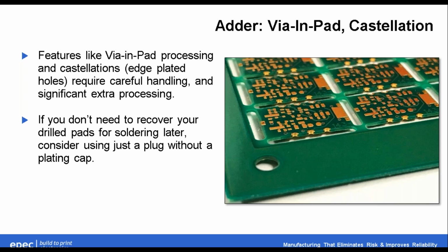So, again, sometimes you can't change your board size. Sometimes you're stuck with what you're stuck with because it has to fit into an enclosure or a rack rail or something. But when you have the opportunity, you can look at something like that matrix and you can try to fit your board accordingly. And again, involve your contract manufacturer, because they might need rails along the edge of the board to hold things through conveyorized equipment. So your board size might look good, but when they put it on their panel, it might blow the material utilization. So there's a lot to think about, but there's a lot of money to be saved as well.